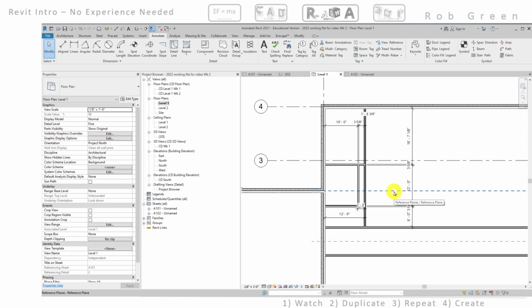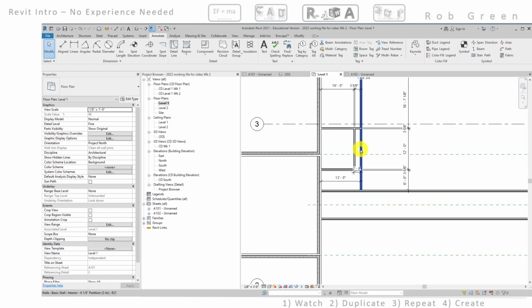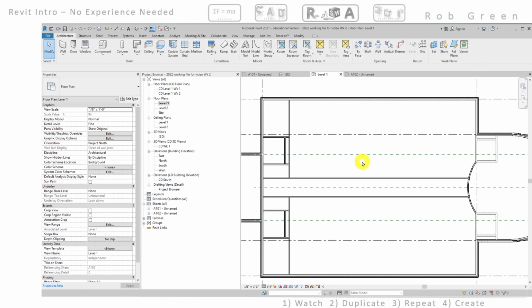And so what I'm going to do is, off camera here, I'm going to delete these dimensions. I'm going to select these four walls, and I'm going to mirror them about my center reference plane. And so next we're going to be drawing some vertical lines, vertical walls, or north-south walls here. And then we'll put in some what I would call chamfers around those hallways.